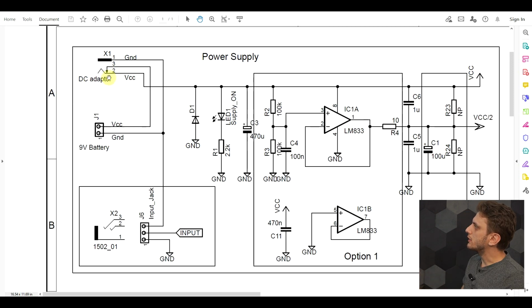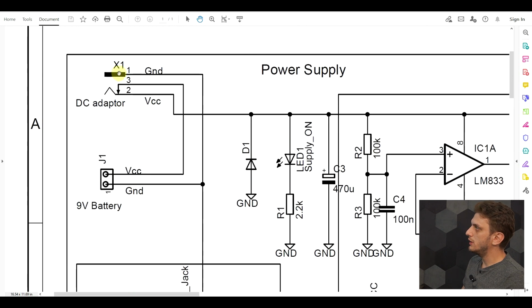So a normal connector for a DC adapter, other than the two pins for the ground and the supply, also has a third pin, which is connected to the second pin, but when something gets plugged into this connector, then this connection disappears. Basically, by using this, I'm connecting the battery to my positive pin through the DC adapter. But this only happens when there's nothing plugged into the adapter. Once something gets plugged in, the battery gets disconnected, and I'm using the DC adapter to supply the circuit.